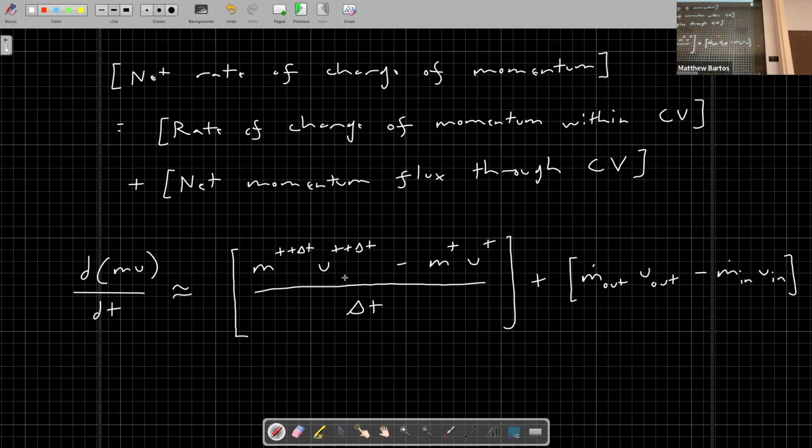Any questions on this? Yes. Can you tell me what flux means again, instead of like a change, basically? Yeah, think of a quantity moving through some area. It's just referring to the transport of that quantity through that area, or the flux of that quantity through that area. So in this case, the surface over which we're looking is the cross-sectional area of the boundary of the control volume. So yes, it's the momentum transport through that face.